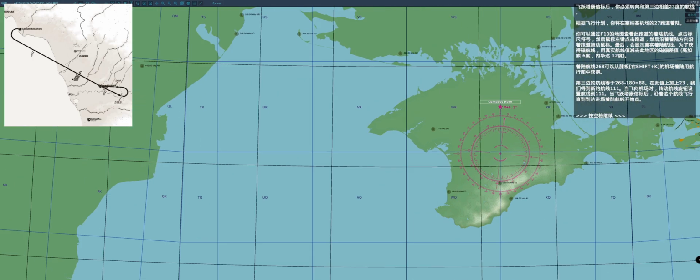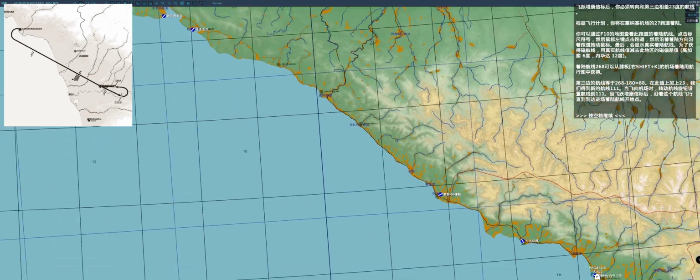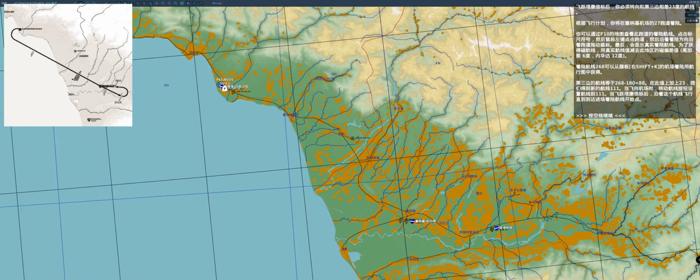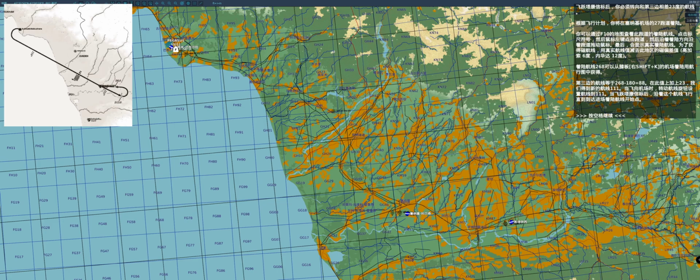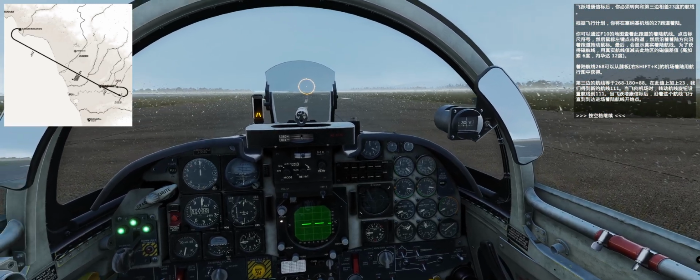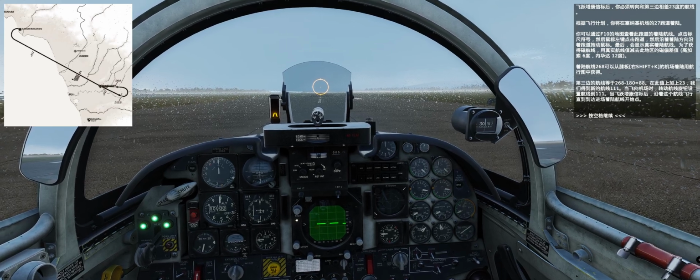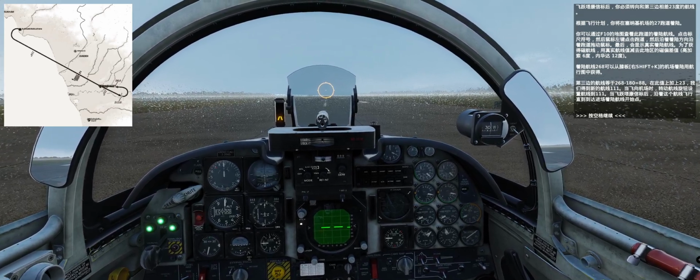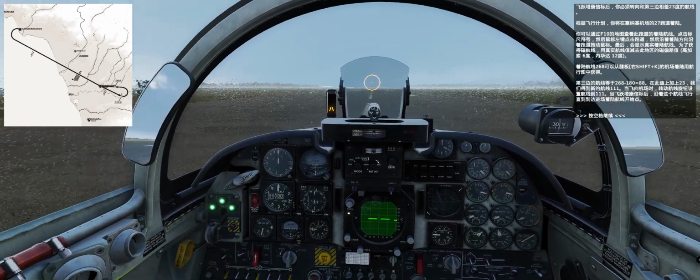While flying towards the airfield, rotate the CRS knob to set a desired course of 111 degrees. After passing the TACAN beacon, fly this course to the point where you begin your final approach landing course. Press space to continue.